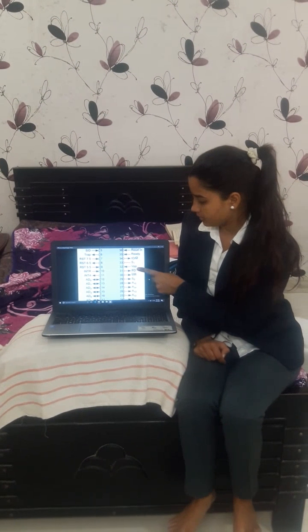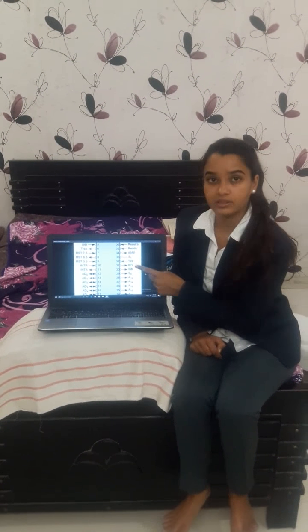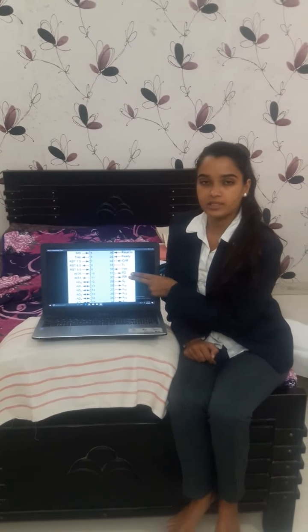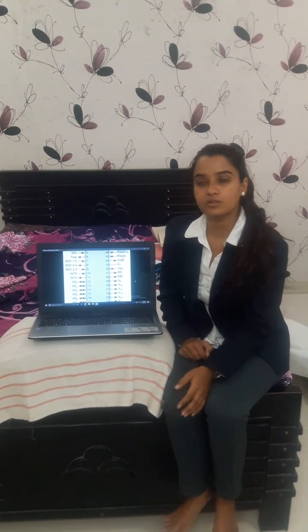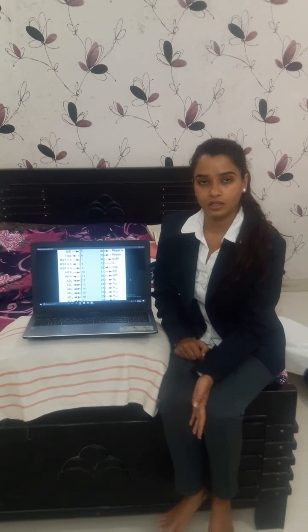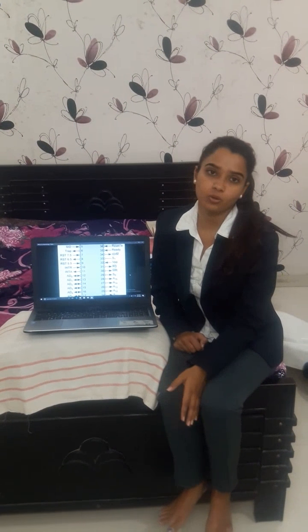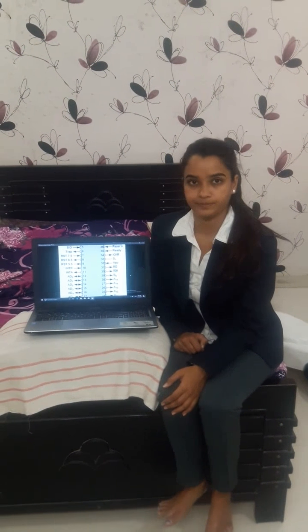The read pin and the write pin indicate that read and write operations are going on. These two pins are active low. To activate these pins, a low pulse is given. These two pins can never go low simultaneously.